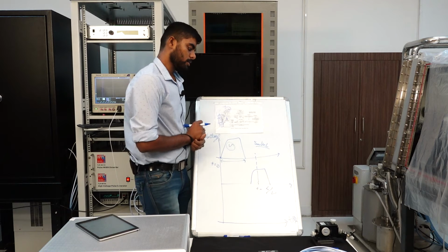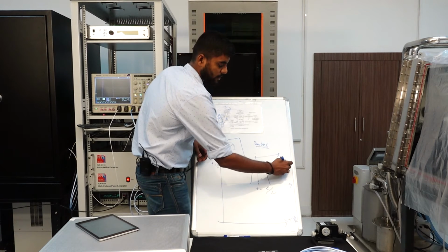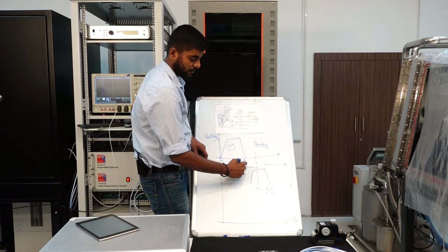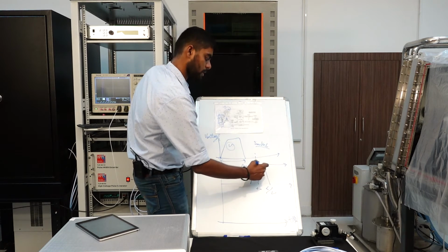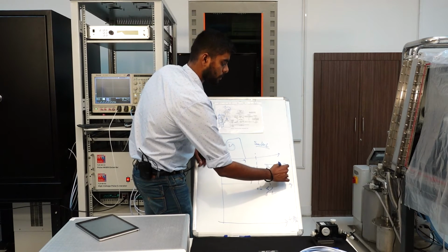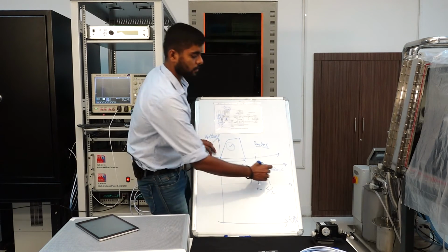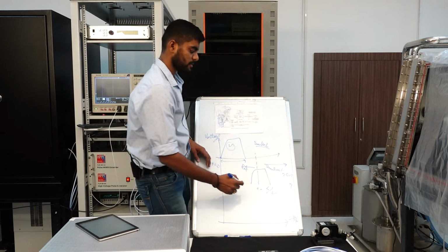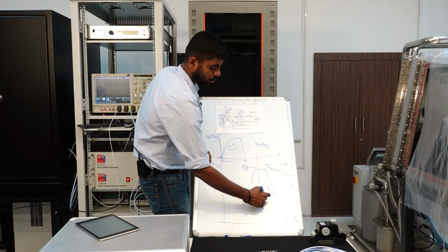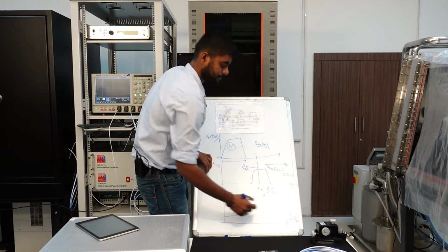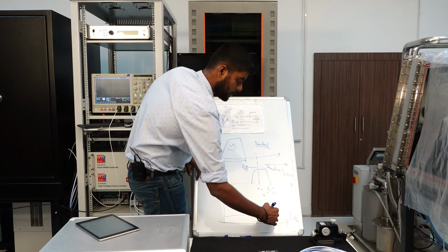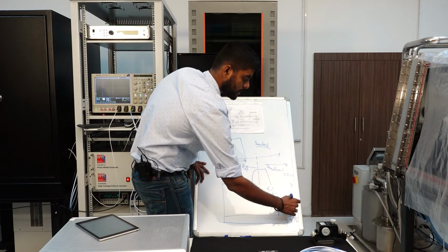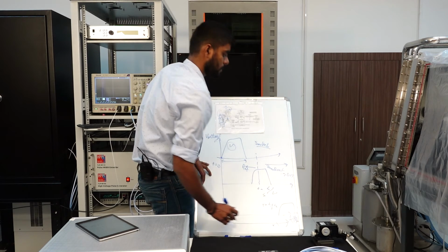Now once the switch has turned on and you have this transmission line network connected ahead, you would have some input wave that is getting reflected back, and some that is incident upon the whole network. This incident wave will then go to your DUT as well. Say the distance from the switch to the DUT is L2. Then at time t equals (L plus L2) by V, the DUT will have this pulse applied to it.